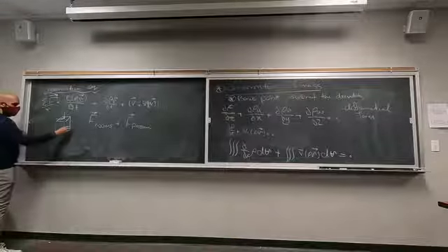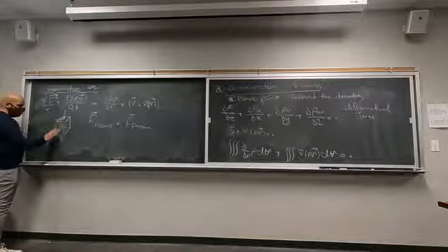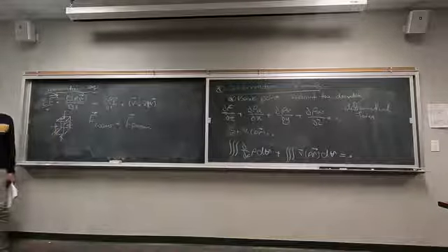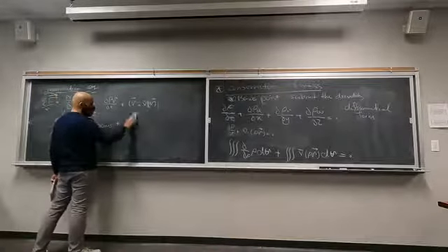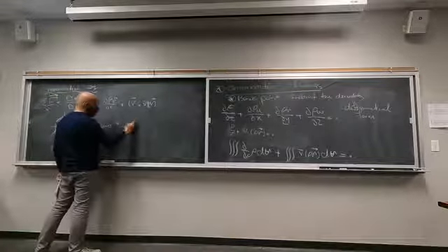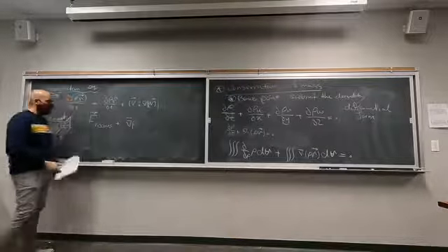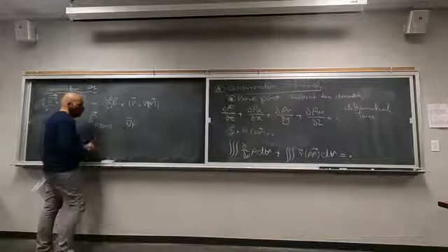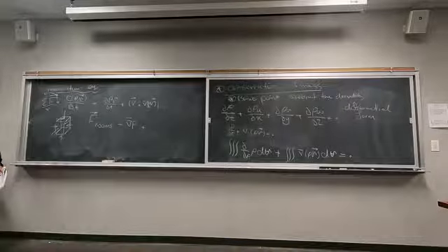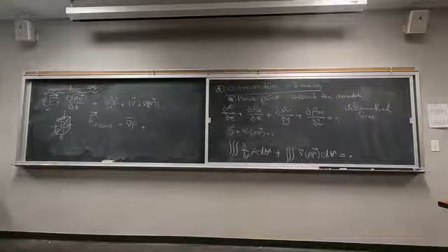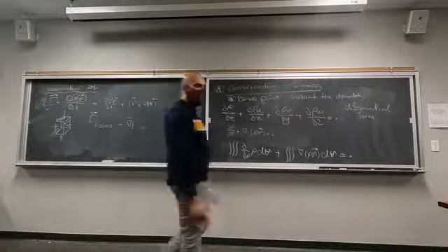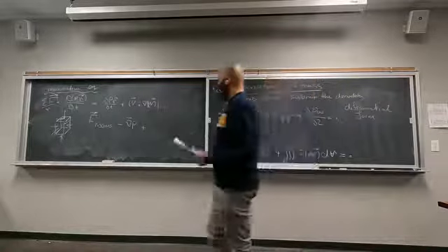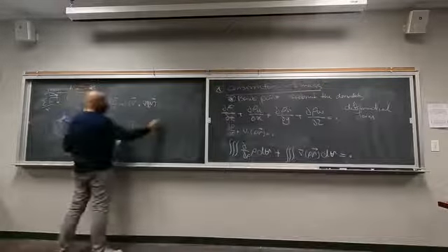Pressure forces are essentially going to be canceled out in all of these different directions if there is no pressure gradient. So if you simplify things, you will essentially end up with the pressure gradient multiplied by the volume, but we have divided everything by the volume before, so we're just going to stick with the pressure gradient, and this is actually the negative pressure gradient. What else do we have? What other force is present here? Weight, right? This fluid has some sort of weight, and we're going to call that body forces, F of B.